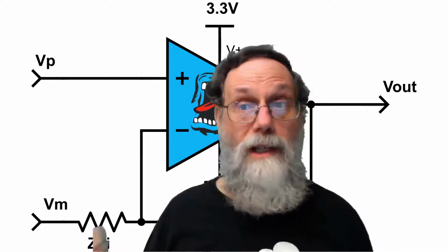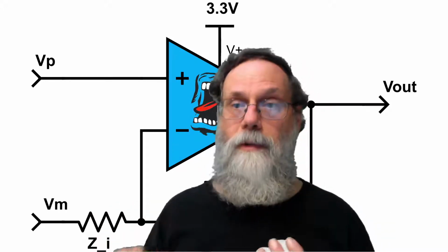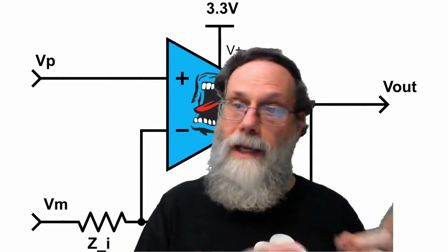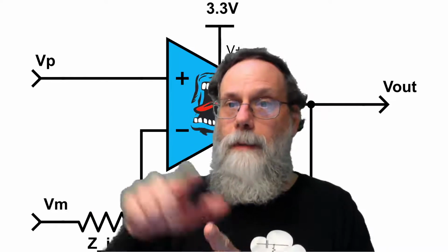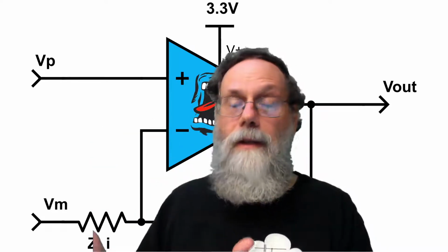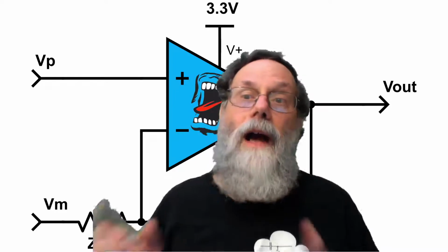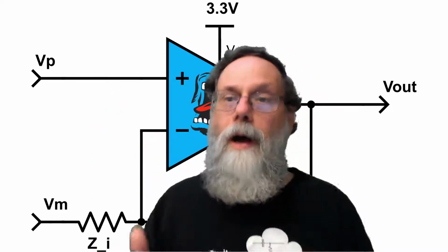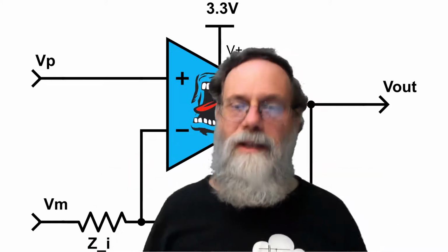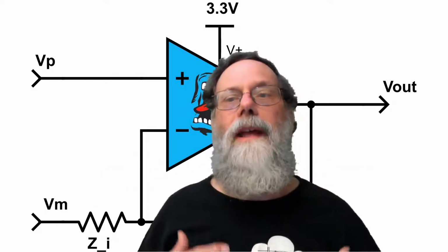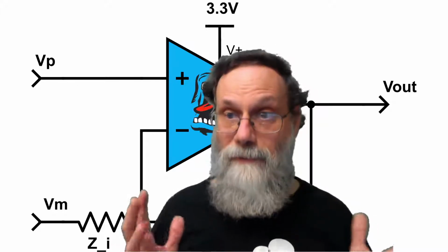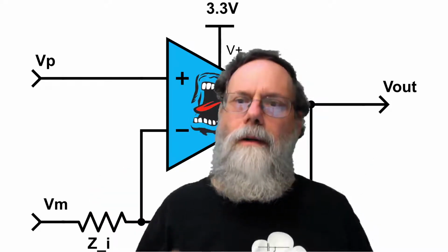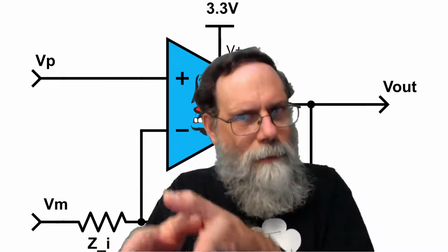And when you get something that isn't what you expect, that difference between the observation and expectation is what allows you to debug it. You can go, okay, it worked up to here. This signal was still what I wanted, but at this stage, the next stage down, it isn't what I expected. It's probably in this region right here, where it goes from working to not working, that my problem is. And that decomposition of the problem is a big chunk of what debugging is about. It's narrowing down from the thing doesn't work, help, to this part works, this part works, this part doesn't.